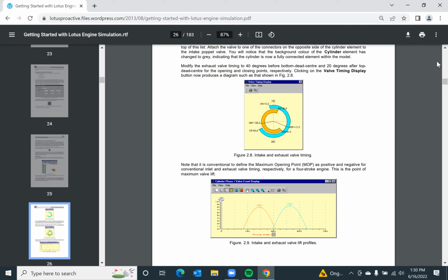And then how do you want it to close? Do you want it to close like this, or do you want to close it smoothly? And remember, all these things are happening very fast. So you need to know how it should be, and then you have to map it to the cylinder phases, because you need to know exactly where the piston is when the valve is opened and closed.